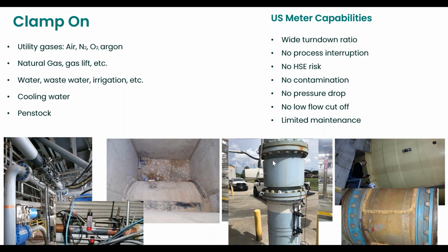If it would have been a turbine meter, for instance, that would have been a very different story. Okay. If it would have been an orifice plate, a very different story as well. But in this case, you are kept as a full bore system using a mag, so that's not a big deal.